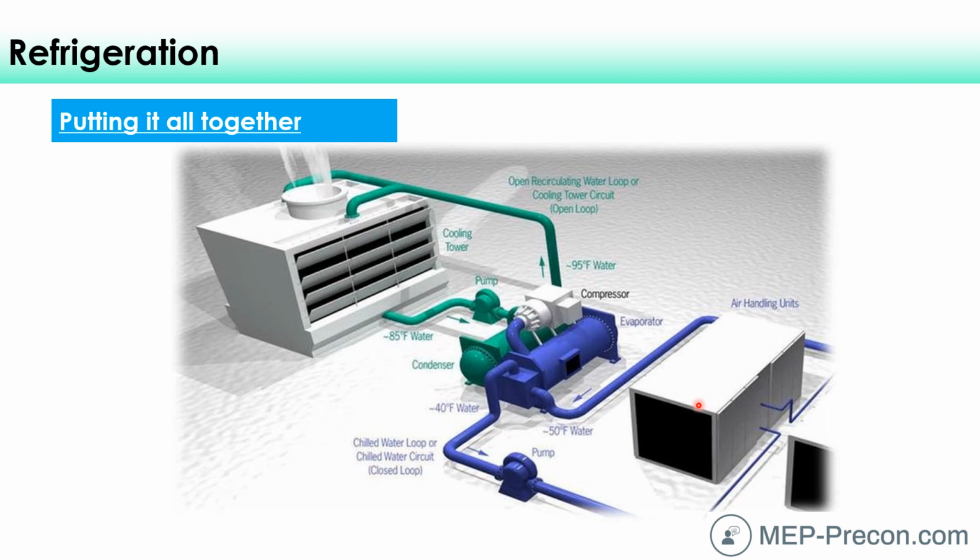What happens to the BTUs? Let's follow those BTUs. All right, so the BTUs are in a state of gaseous refrigerant, because that's what the heat did, it boiled that refrigerant. So now that gaseous refrigerant goes into the compressor. That compressor pumps that refrigerant to a really high pressure, and because of the perfect gas law, it pushes the temperature up to a point where it can exchange heat with the water within this condenser barrel now. So within this condenser barrel, there's some water, and that's how we're going to get rid of the heat that's in the refrigerant. We're going to exchange heat from that high temperature gas to this lower temperature water here.